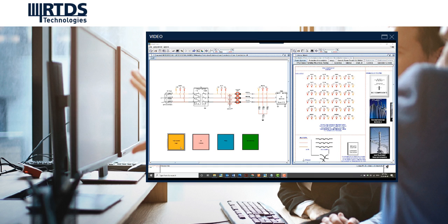And to do so, we're simulating a feeder relay and recloser, which are configured to have a two-shot reclosing cycle, where the initial trip and two reclosing attempts are set to be based on instantaneous overcurrent elements. And the operation will then switch to a slower time overcurrent element to allow the fuses to blow. And we can demonstrate that fuse saving activity with this case.